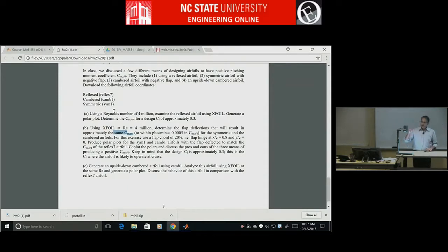And in pplot or Xfoil for that matter, if you hit an enter, that's like a blank line in the batch file. So at the end of all, you do everything all the way to the end till you close pplot, and you do that also. Like, what do you do, 0 or something to close it? Yeah, so you put 0 there. Then the next time you just go and say pplot less than the batch file name, and it'll just go through all of those as if you were typing it one by one.